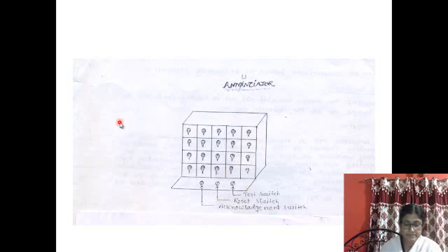Then the fault sequence. Fault sequence means whenever any fault occurs in a particular process control loop corresponding to a particular channel, then the respective channel of the annunciator unit becomes unhealthy. So the corresponding channel lamp will glow, as well as the hooter will turn on, in order to produce the audio and visual alarm. This is called the fault sequence.